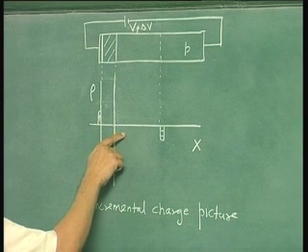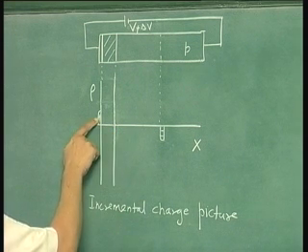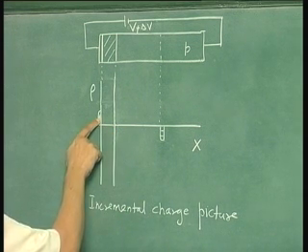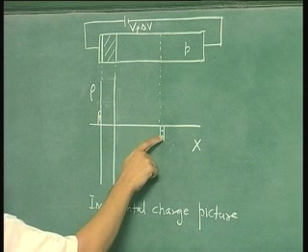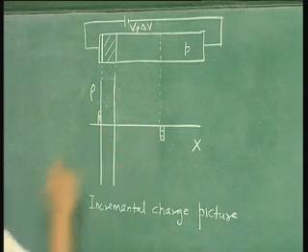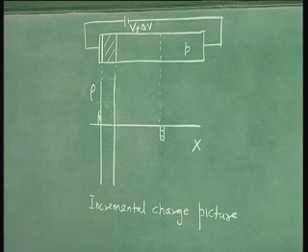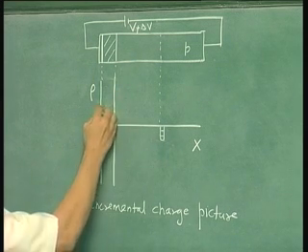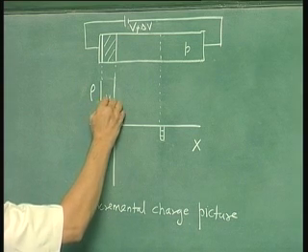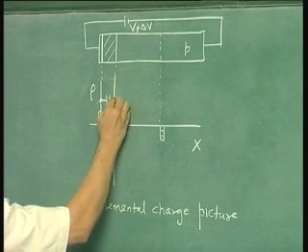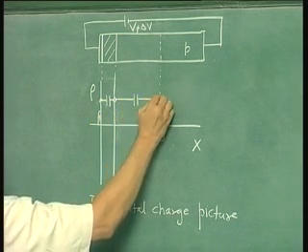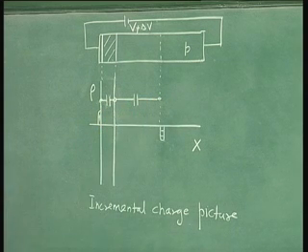You want to know why a charge here at the gate and a compensating charge at the edge of the depletion layer, this kind of a picture results in a capacitance of this MOS capacitor, which is a series combination of the oxide capacitance and the depletion layer capacitance. You want to understand how this is possible? A very simple way of explaining this is as follows.